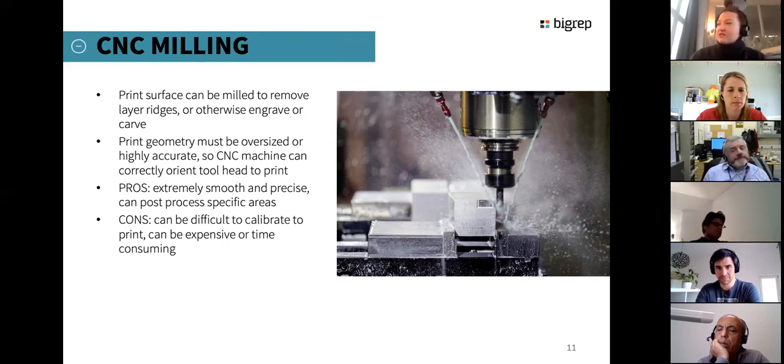The rest of the materials shouldn't behave too differently. It would take a little bit of experimentation, but I'd say roughly the same, except for again TPU. So anything that you're going to abrade with a mechanical process, TPU is going to be a problem. The rest kind of give or take similar, and PLA ultralight super easy.